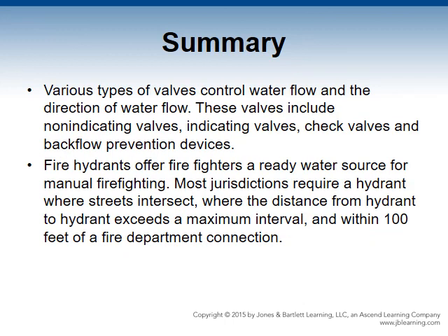Various types of valves control water flow and the direction of water flow. These valves include non-indicating valves, indicating valves, check valves, and backflow prevention devices. Fire hydrants offer firefighters a ready water source for manual firefighting. Most jurisdictions require a hydrant where streets intersect, where the distance from hydrant to hydrant exceeds a maximum interval, and within 100 feet of a fire department connection.